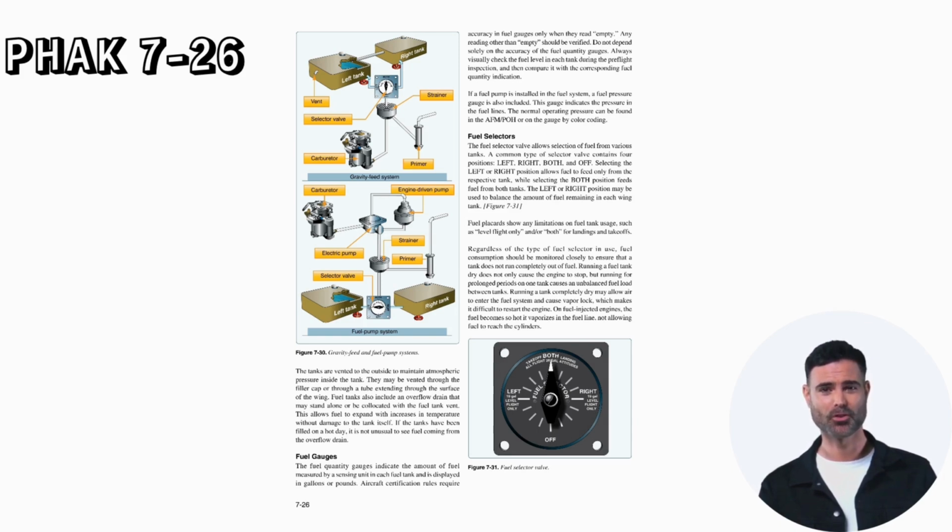Fuel tanks also include an overflow drain that may stand alone or be collocated with the fuel tank vent. This allows fuel to expand with increases in temperature without damage to the tank itself. If the tanks have been filled on a hot day, it is not unusual to see fuel coming from the overflow drain. Fuel gauges. The fuel quantity gauges indicate the amount of fuel measured by a sensing unit in each